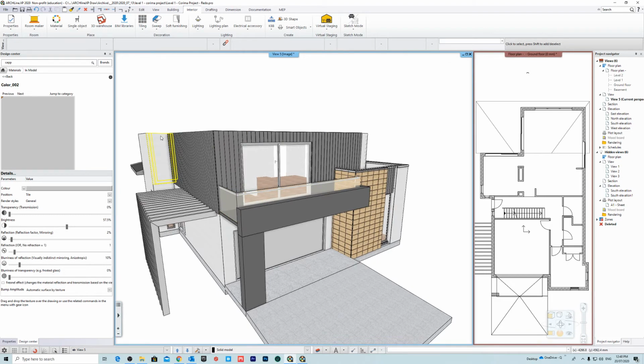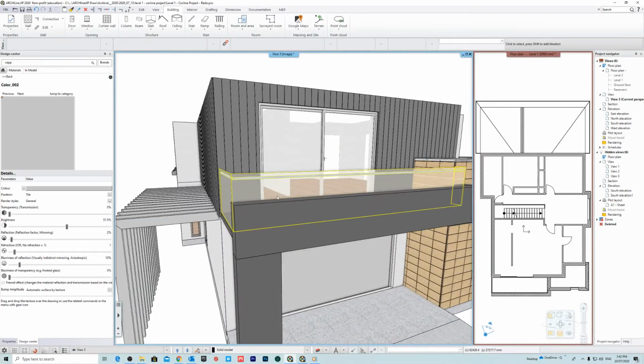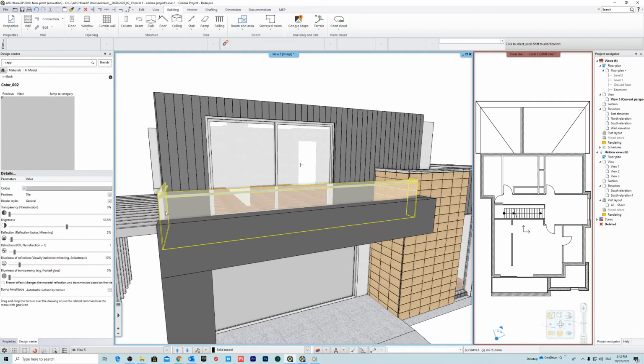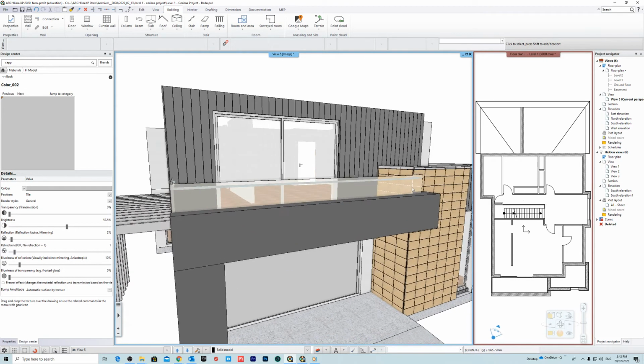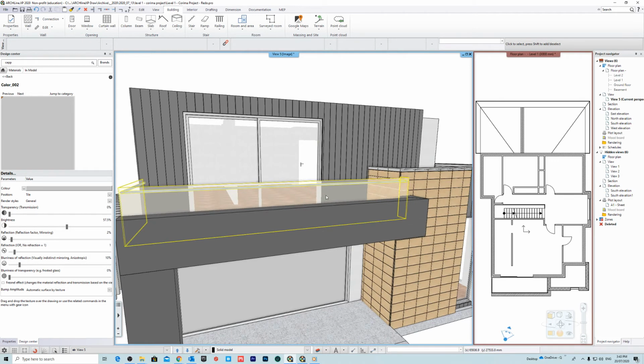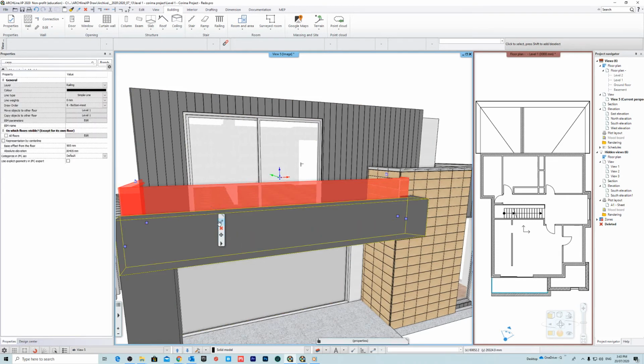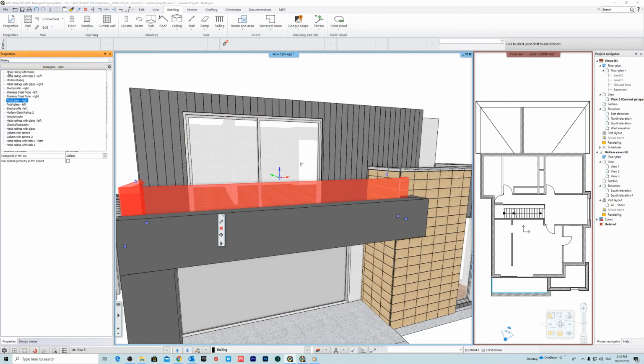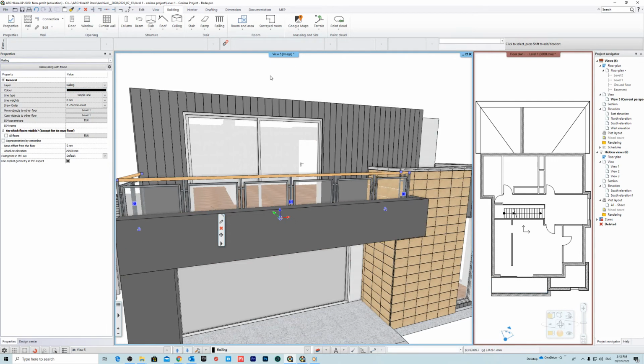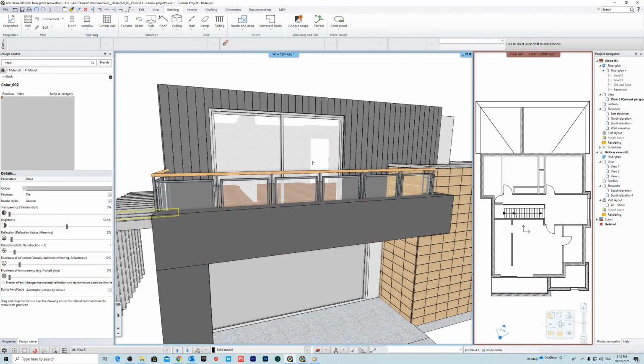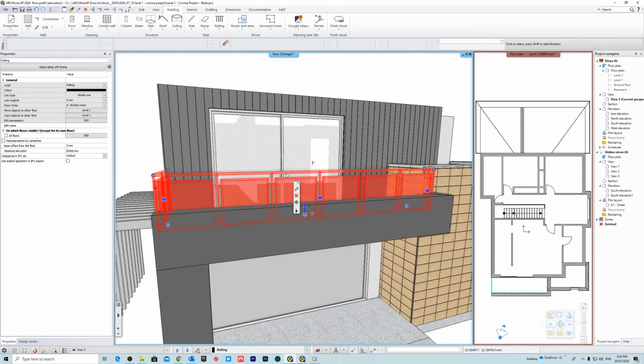We're actually going to turn this into a modern railing. I want a modern railing that has spaces in between, and I want the handrail to actually be on the top. So this is not the railing that I really like, and I want something a bit more modern. So I'm going to change this to glass railing with frame, and I'm going to make some modifications. Okay, so we'll just go on edit.